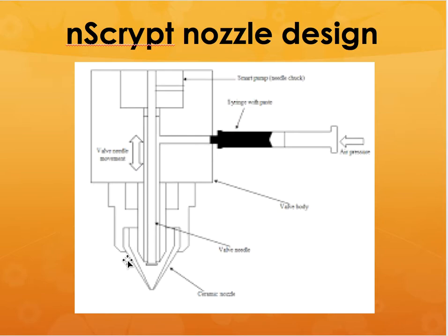But because of this really unique type of nozzle design, it allows these materials to be delivered at extremely high viscosity, because once it is delivered it needs to solidify immediately. The next thing is that, for example, if they have to be sintered, they should not shrink by a whole lot. So the higher the solids loading, the lesser the shrinkage. So that's the main advantage of this very unique nozzle design.